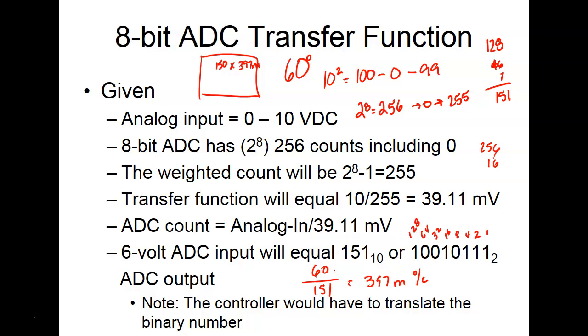And then you can take the temperature that you know, like freezing, and divide that by what you actually get out of it, and you can calculate it this way. So we'd have to use the math instruction, the multiply instruction. What's nice about a programmable logic controller is that it does math. If you can calculate these transfer functions, you can take these analog sensors and display the quantity that you want, and not the 151. The 151 doesn't really mean anything when it actually means 60 degrees, or 60 degrees of motion, or a 60 degree temperature.